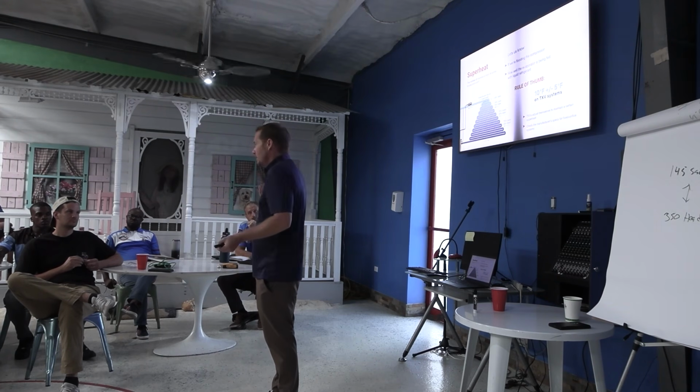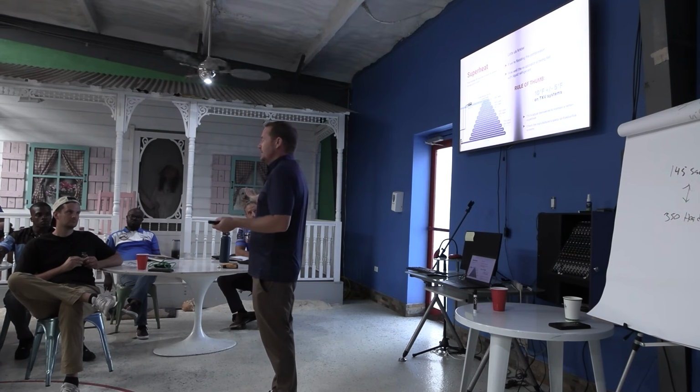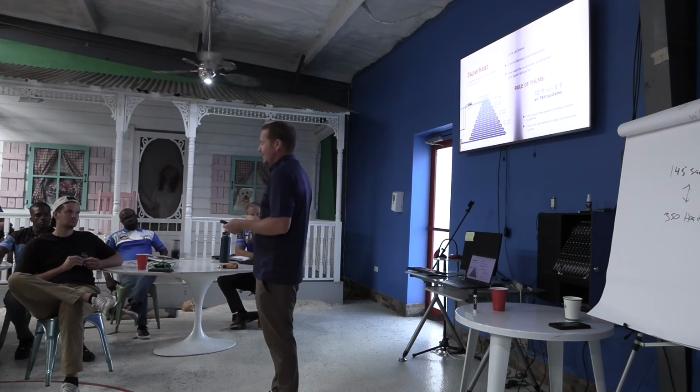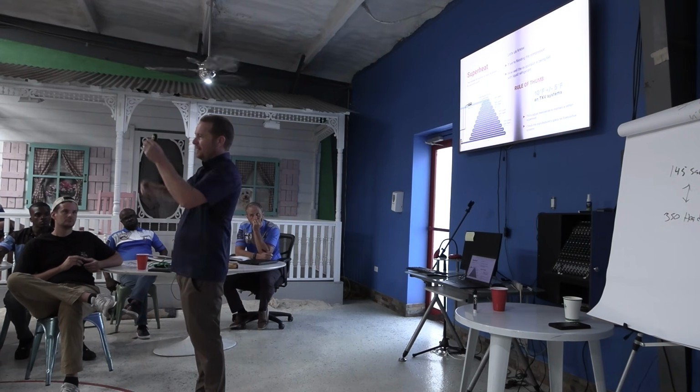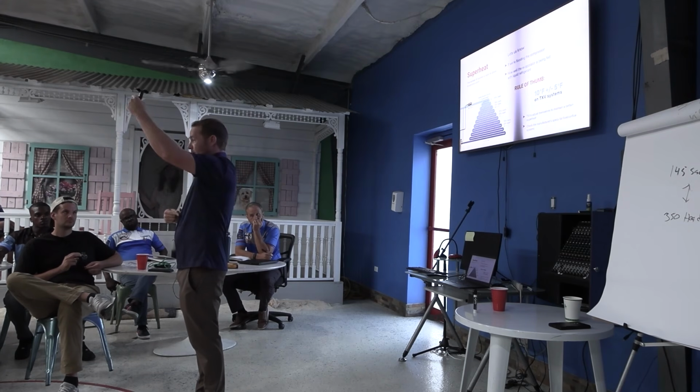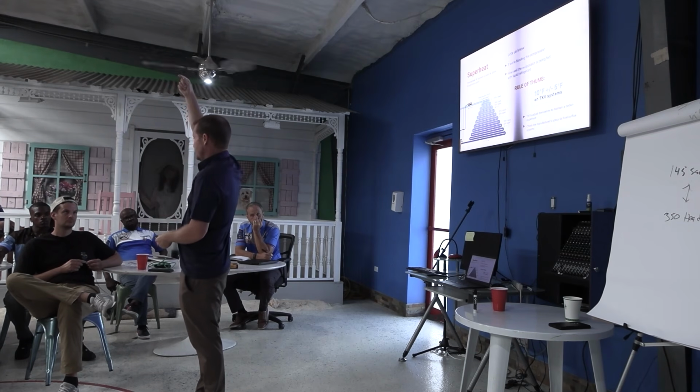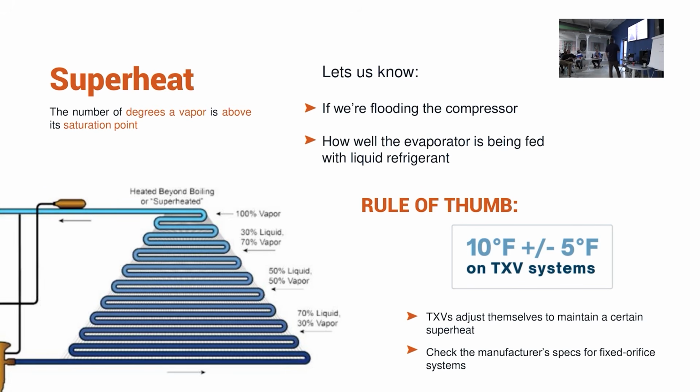Now, why would you do that? Well, the argument is that you could actually put less refrigerant in the system and now have less risk of issues potentially with that. Now again, that's not probably realistic, but you have to think about that separation. If it was going the other way, you potentially might need to, because you actually get pressure loss as you go up the tube. Knowing your superheat.